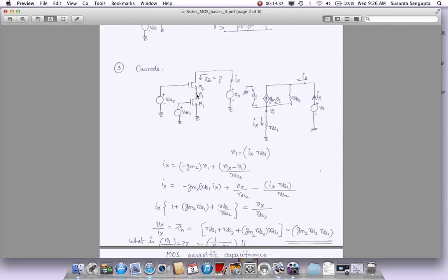Okay. So if this voltage is V1, the gate of this device is AC ground. This voltage is V1. So what is VGS of this device? VGS of this device is minus V1. Right? We are talking VGS. So if this VGS is minus V1, what happens to the current? The current actually goes the other way. It goes from bottom to top, right? It doesn't come down because VGS is negative.